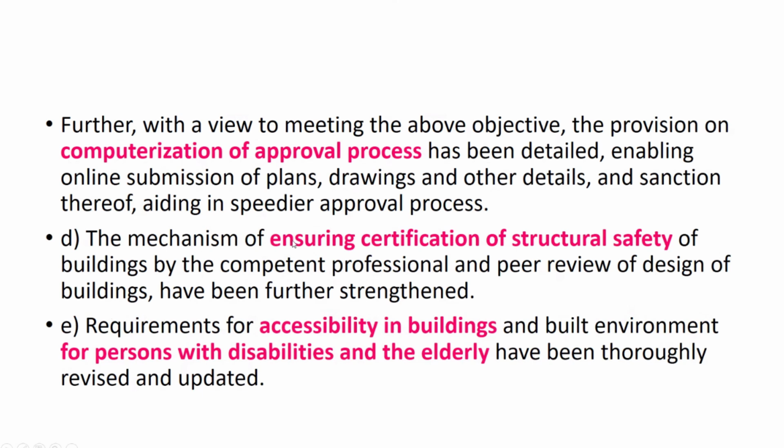Therefore, in general, for office buildings, for every part of the bay to be served by the ceiling fans, it is necessary that the bay shall be so designed that the full number of fans can be suitably located. Otherwise, it will create ill ventilated pockets.